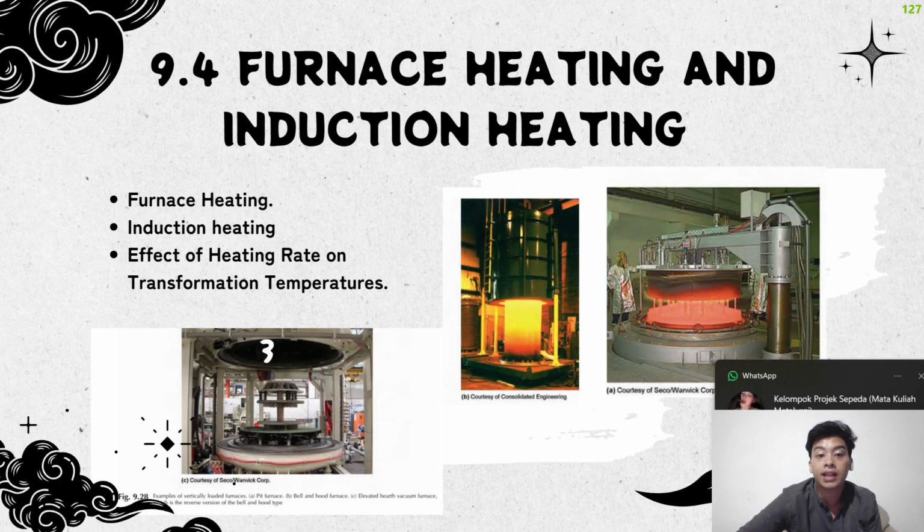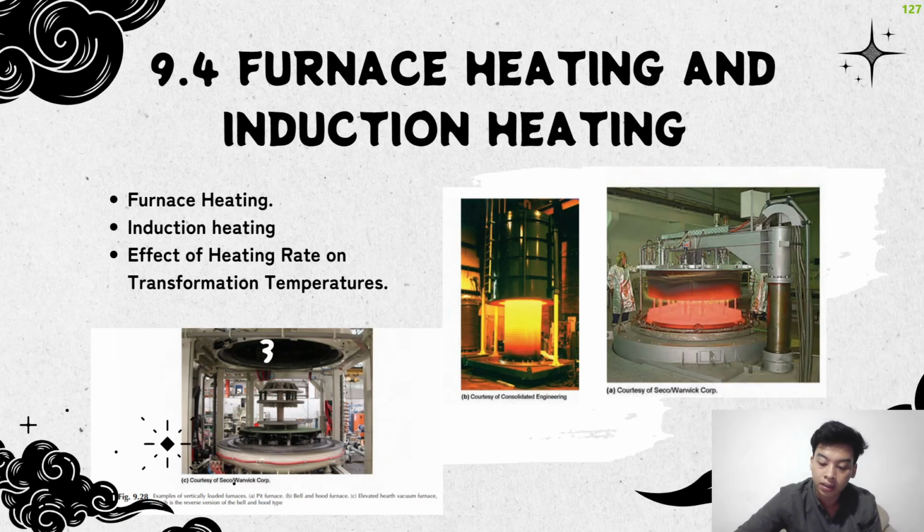Furnace heating and induction heating. Heat treatment of steel involves a wide variety of methods for annealing, normalizing, hardening, and tempering. Fuel-fired or electrically heated furnaces are used in a wide variety of configurations with various media. Furnaces are also used for thermochemical treatments such as carburizing or nitriding.